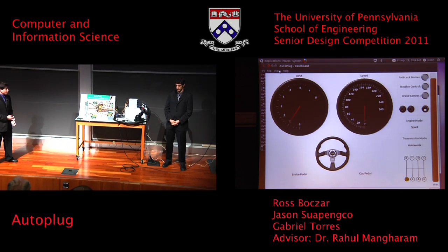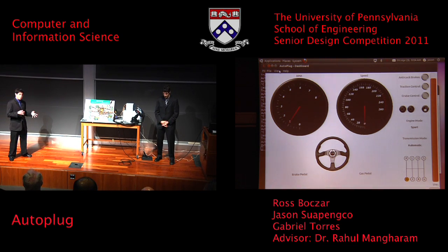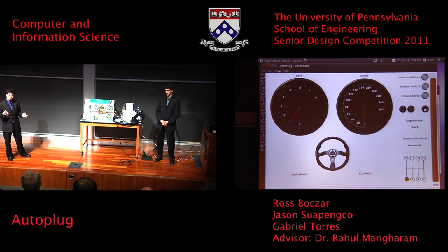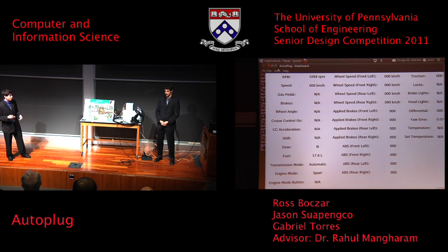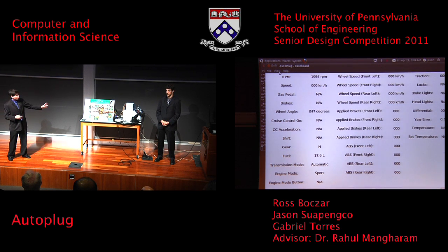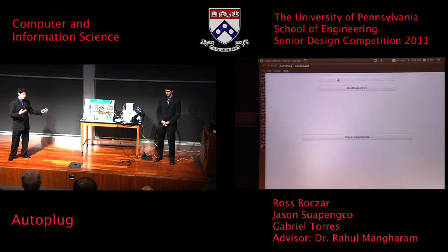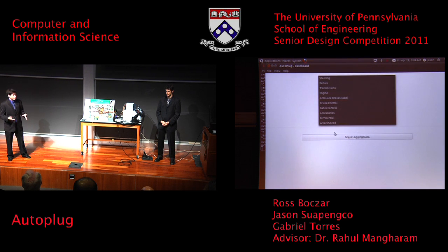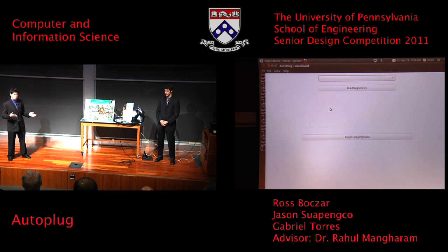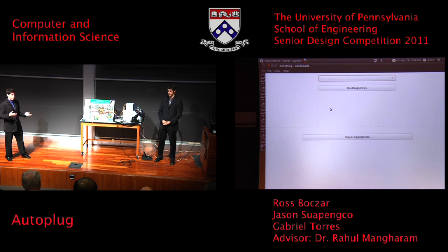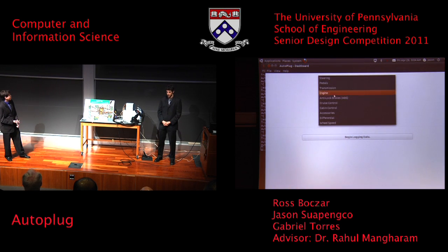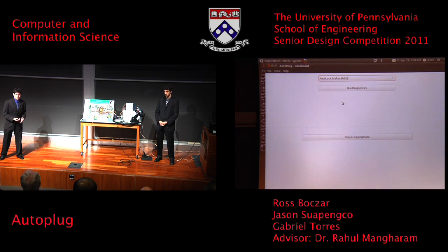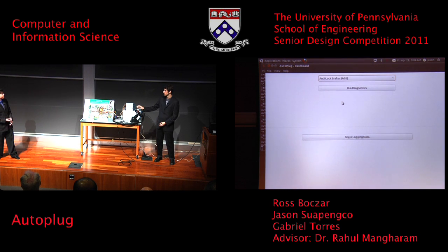The middleware layer connects to something called the CAN protocol, which is the accepted method of communication between microcontrollers in cars today. The CAN bus is the way that each of these ECUs connect to each other and communicate. Using this powerful bus, we can connect the computer to take advantage of the wealth of information that's currently being transferred between these ECUs and perform functions such as car visualization for the data being transferred.